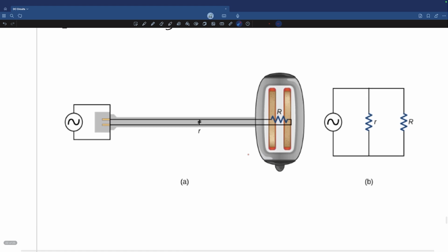All right. So that's showing a short circuit here. This is if there is a contact where there should not be any contact. That's when it's called a short circuit, and the current, instead of flowing through the higher resistance path, now takes a shorter path this way. That means the resistance being low, the current is going to be really high, and it'll produce a lot of heat, and there's chance of fire. So short circuits are dangerous.